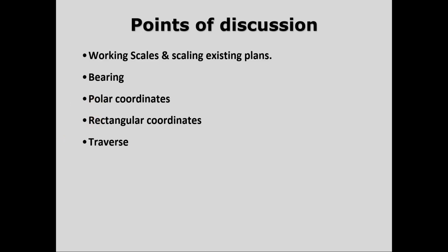Points are very important. When I'm saying points, guys, I'm talking about survey points. Survey points, you name it. They specify, for example, the starting point of a road and the end point of a road, or a location on a surface, a particular point on a surface, as we discussed before. It's made of a group of points. So each one of these points has a certain location. So it's very important to learn how to obtain, interpret and read these locations. So we've got two different methods: the polar coordinates and the rectangular coordinates.